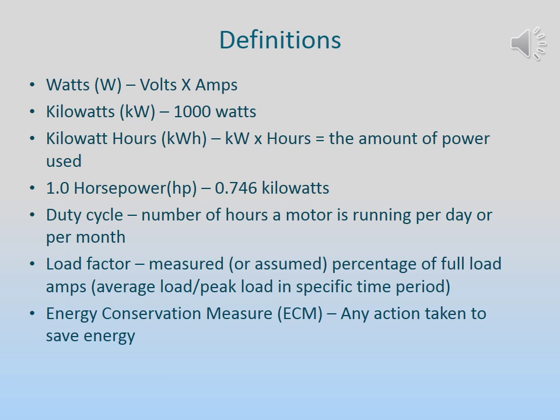Our focus today will be equipment. It is going to take motors to run the pumps. It is going to take motors to run blowers. So we deal with motors. Duty cycle: number of hours a motor is running per day or per month. We want to know this information on each piece of equipment in order to assess the cost to operate.